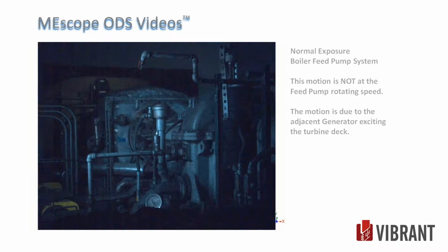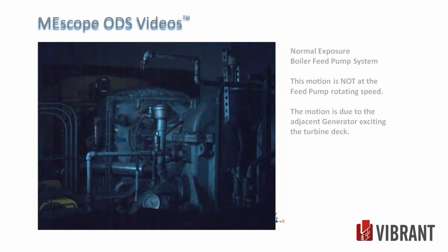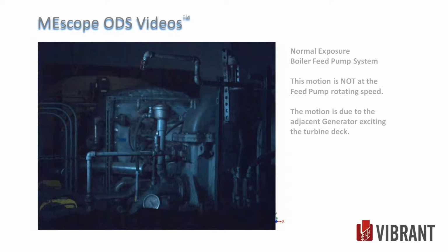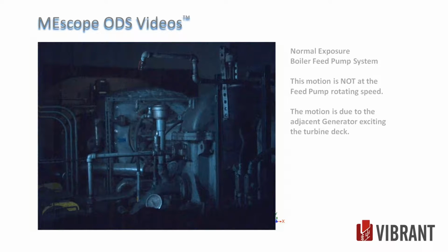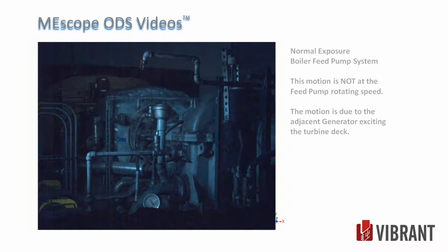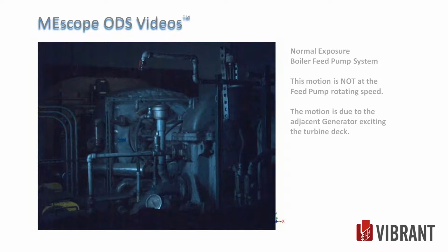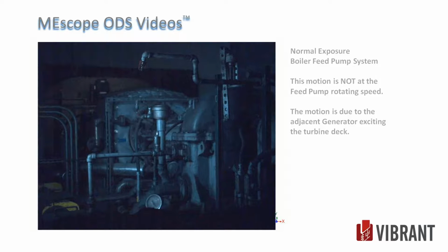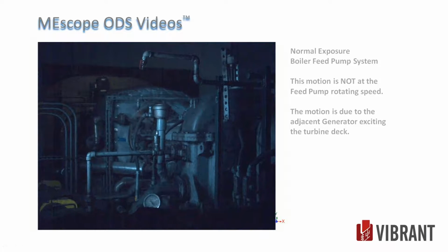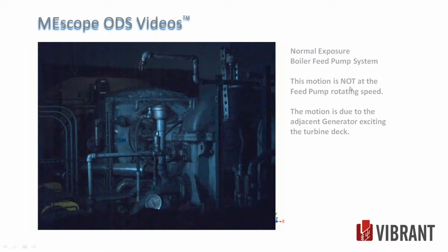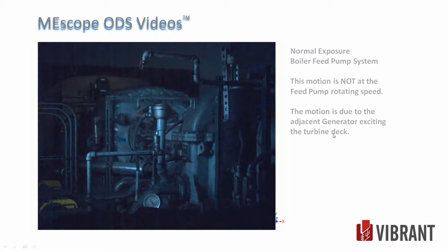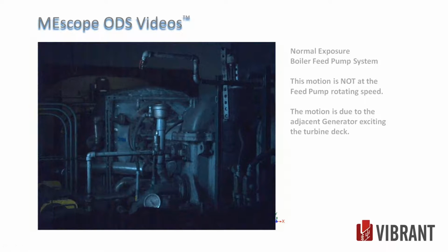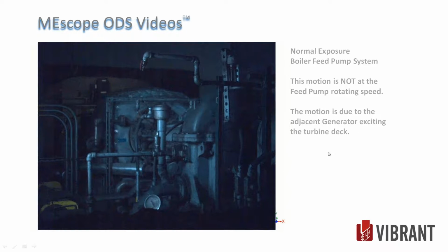Here's the first video that I took. And you look at that and you say, no, I must have bumped the camera. The camera must be sitting on something that's vibrating. In fact, it was mounted to the floor, but everything's going, on the turbine deck. So normal exposure, boiler feed pump system, the motion is not the feed pump speed. It's the motion generated from the adjacent generator exciting the turbine deck.